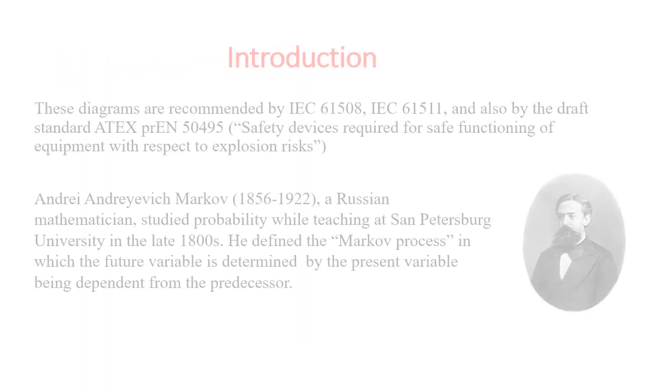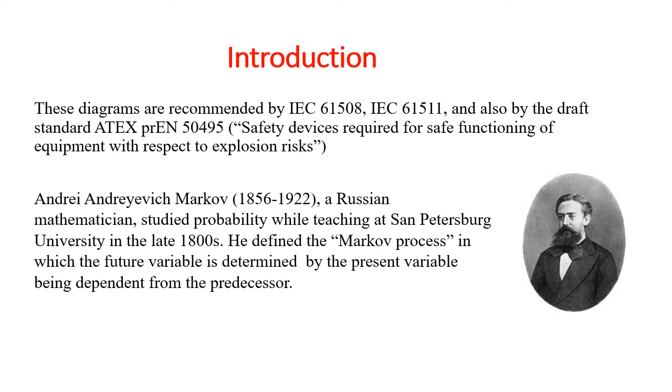SIL verification and related functional safety issues are mainly governed by the two standards, IEC 61508 and IEC 61511. Markov analysis is basically supported by both of these standards. There is another standard, which is EN 50495, that is mainly related to identifying the explosion risk of devices, and that also uses Markov analysis.